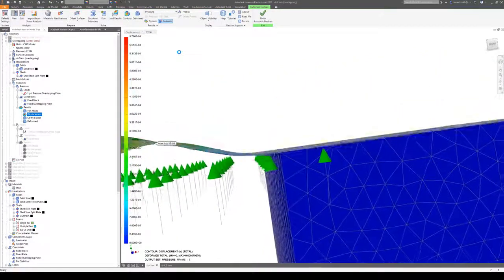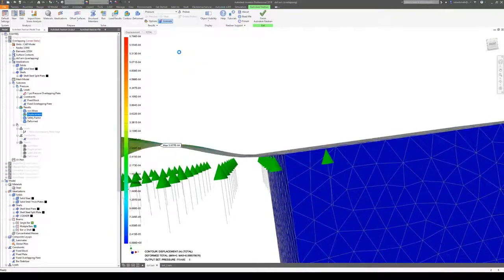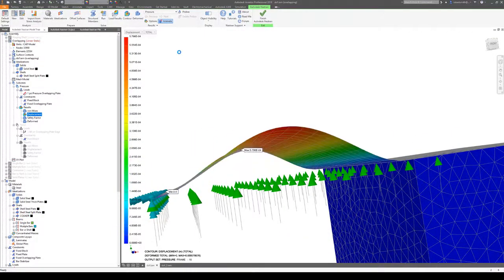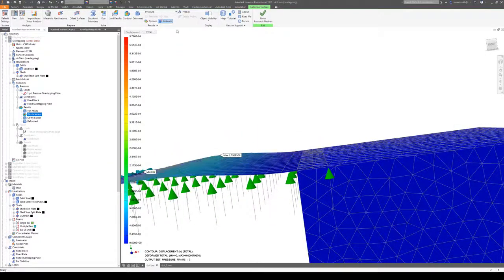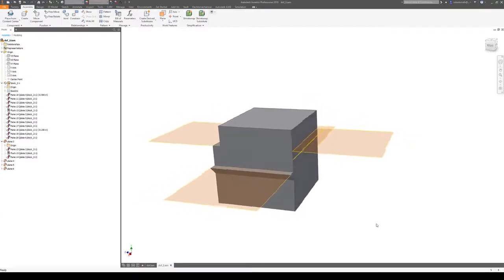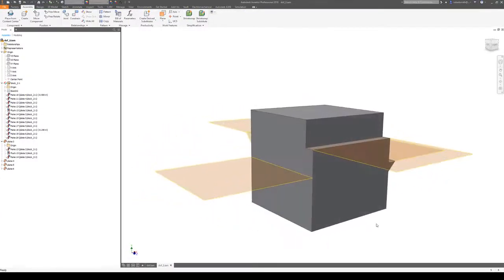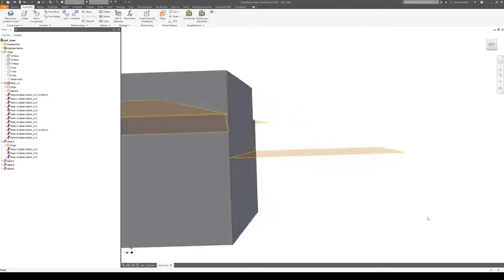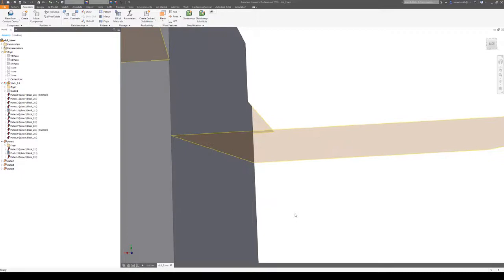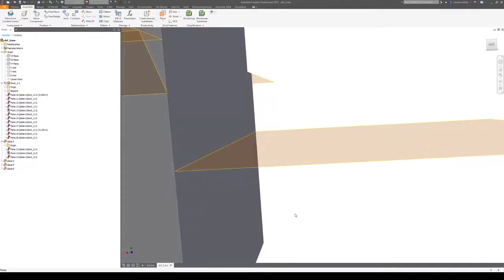And sure enough, I get the bending that I expected on both ends. Now in this other model here, I've just shown a few other ways that you can deal with that. Let's say this is a condition where a plate meshed with shell elements is going to be meeting up with the face of a solid structure meshed with solid elements. There's no way that I can overlap these two as modeled, like I did when it was at the top.